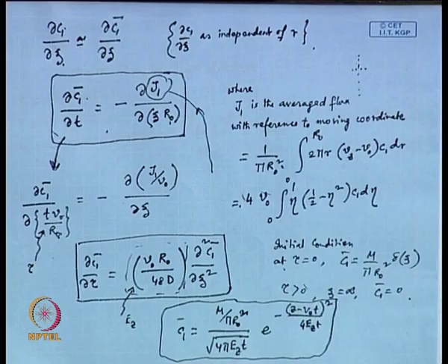So, if somebody is working with a non-circular cross section, still there will be Taylor dispersion. Okay. Of course, the dimensions, one has to be much higher than the other. When we talk about flow between two parallel plates, the distance between the two parallel plates is much smaller than the width of the channel. So, one is height, another is width. If I put it, then height must be much less than the width, and we are working with this. So you have the dispersion between the two parallel plates. I mean, do you understand what I am trying to say?